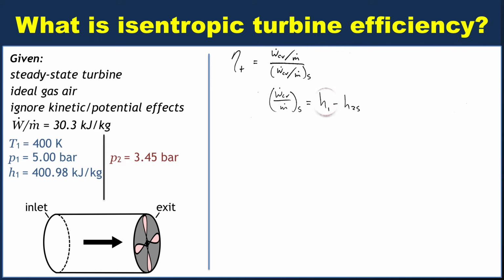The next step, of course, is to figure out what to do with H2S. All right, so here's where we use these weird pressure ratios. And so one of them in your lecture notes is P2 over P1 equals this new weird variable PR2 over PR1. So, things you need to know about the PR variables. One, they're not pressures.